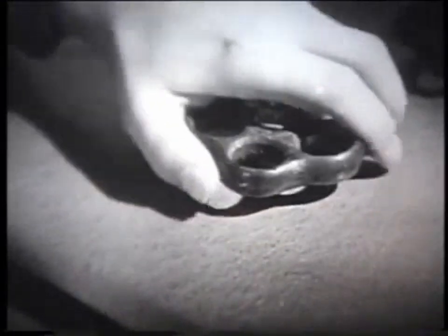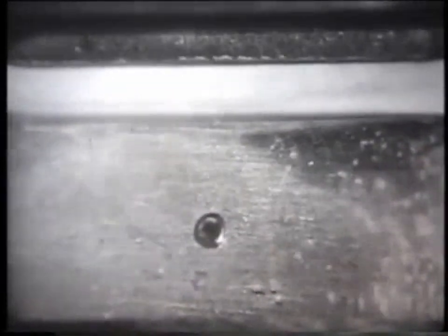In an electrochemical system, the workpiece is the anode, and the tool is the cathode. The gap between them is filled with an electrolyte solution. Turn on the current. The material of the part, you see it from above, dissolves evenly. But if the part has a protrusion, metal removal proceeds more intensively on the protruding part, where the interelectrode gap is smaller.